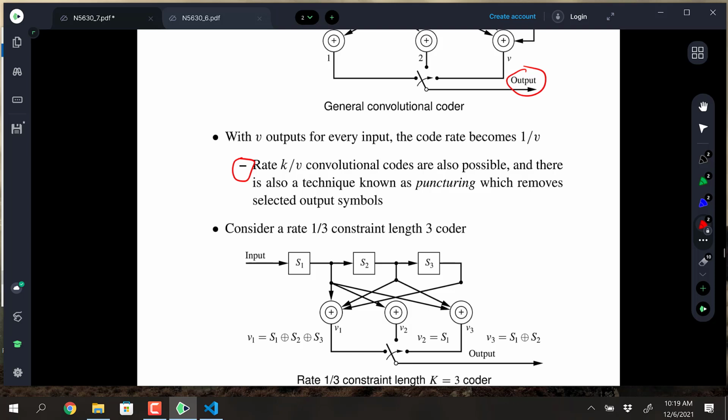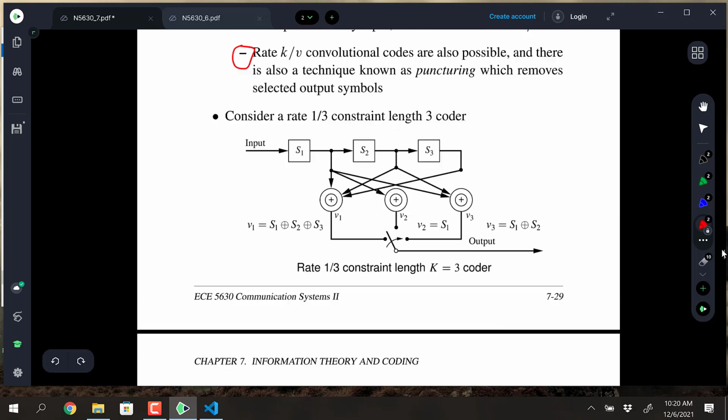Plus, with a straight convolutional code, you're going to have, at best, 1 in and 2 out. You can't do anything smaller than that. So that's a rate 1/2, but with puncturing, you can actually bring it up to, say, 7/8 or 3/4 or something like that. And that's the really important thing about puncturing: you can raise it above 1/2, which means your serial bit rate in the channel doesn't have to simply be doubled. It can be just fractionalized. If it was a rate 3/4 code, the serial bit rate now has to be 4/3 of the nominal bit rate in the system, which is more manageable. Or if it's 7/8, it would be 8/7 the serial rate. People in the satellite community were the first ones to really get involved with convolutional coding, and it's just a standard. So this is the rate 1/3 example.